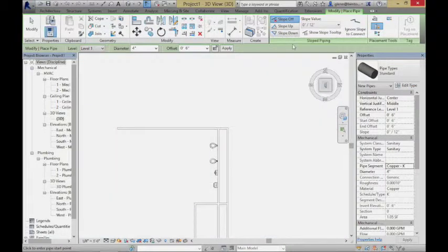Relatively low. I have the notion of, should it slope off, should it slope up, or should it slope down? Okay, and I'm actually going to have it slope down relative to the direction I'm drawing it. It's kind of from start to finish. You can think of that, I'm going to either go from the center here, I'm going to run the sewage this way. I could either come here and slope up, or I come here and slope down, either way. Also, relative to that offset I'm putting in at 6 inches, is it going to be going 6 inches, 5 inches, 4 inches, or is it going to go 6 inches, 7 inches, 8 inches? Either way, I'll think about it as going slope down.